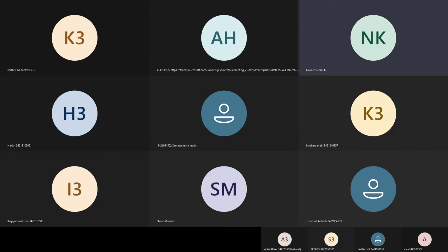The code book which is used for steel section design is IS 800:2007. This is the Indian Standard for design of steel structures. You can use that code, and you decide the diameter of the bolt also. After deciding the number of bolts and the diameter of the bolt, you detail it. This is the thing related to the connection.